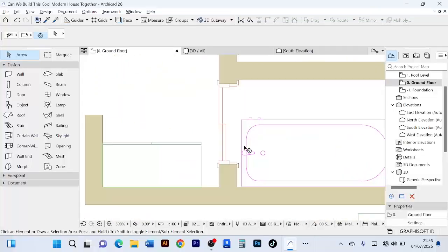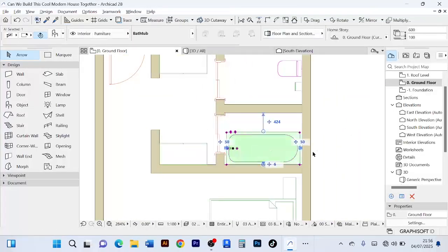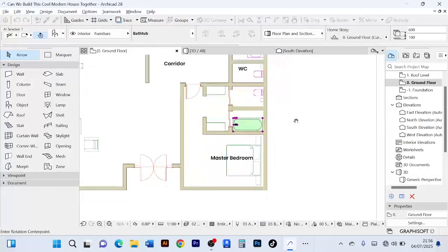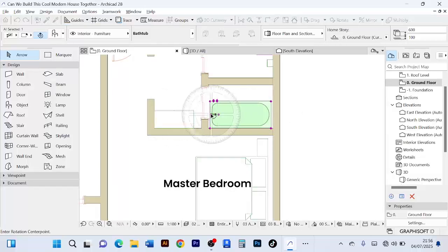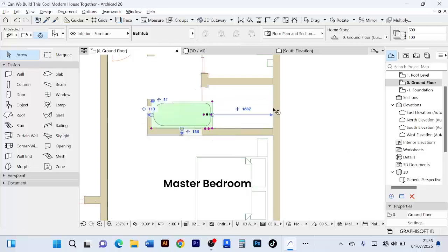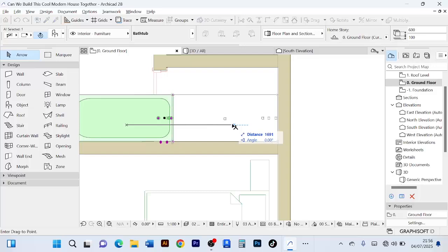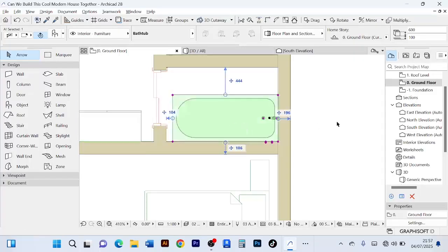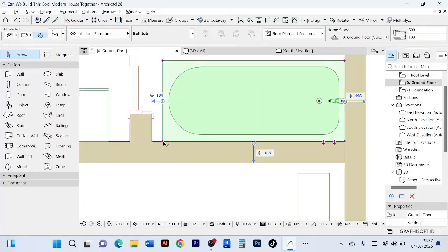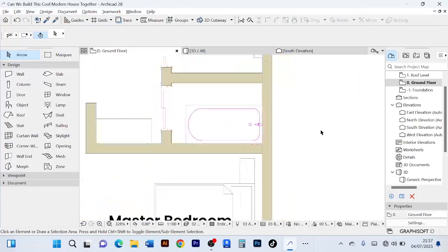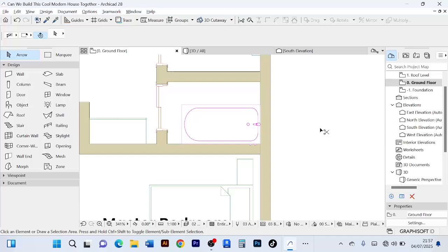Then you also have your jacuzzi here. This jacuzzi, I'm going to change the orientation. It can't face like this. I'll press Control R, then I'll just draw a line here. Then I can rotate it all the way at 180 degrees. Then I'll use Control D to drag it inside, just like that. Then of course you can use this to reduce the size if you wish to. Then I'll just leave it at that so I can save my work.